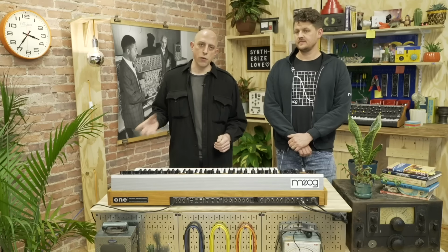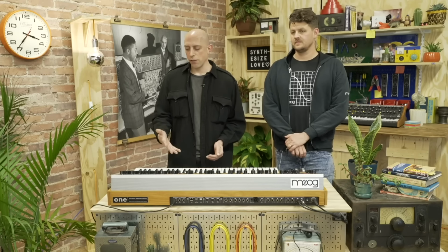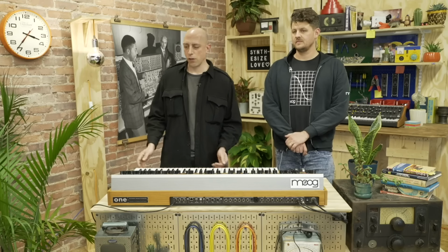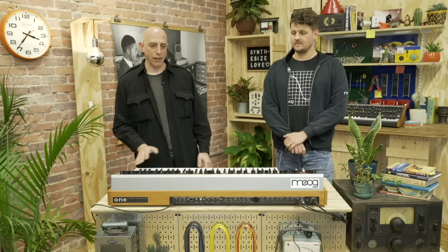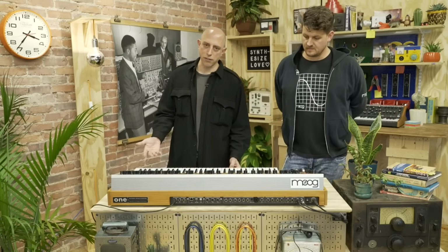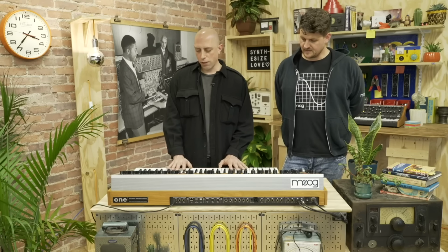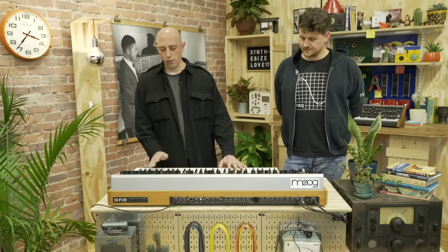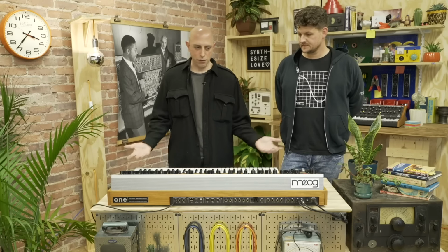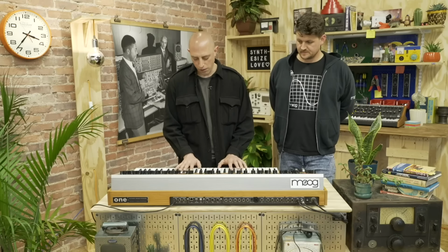But there are just a few cases where that is the case, and in almost every case, if you're not using the synth effect, definitely the dry signal is 100% analog, and even if you are using the digital delays on the synth effects, the dry portion is still 100% analog. So mostly the dry signal that you hear is going to be analog, and if you disable all the effects, everything is end-to-end analog, no A to D conversion anywhere.